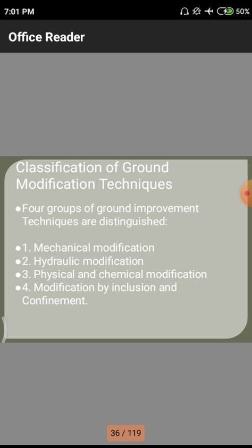Here we mainly use mechanical equipment that simply moves over the soil, so due to the huge force applied on the soil while the vehicle moves over that area, densification occurs.